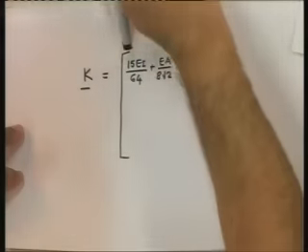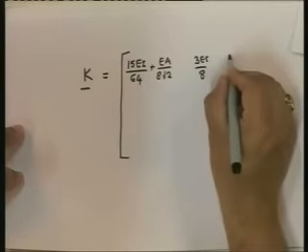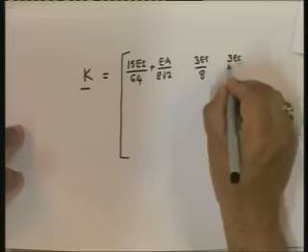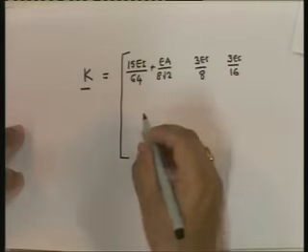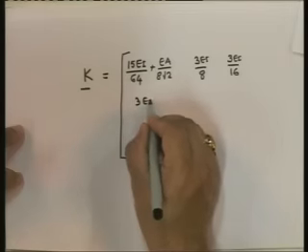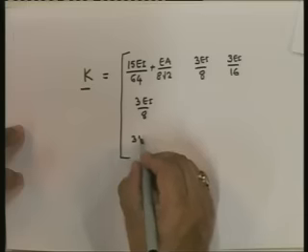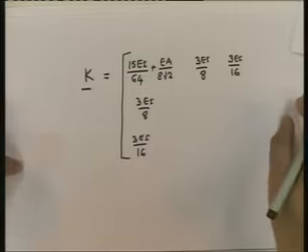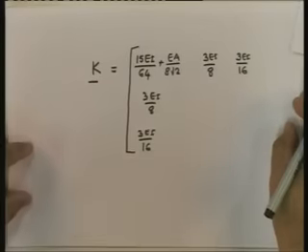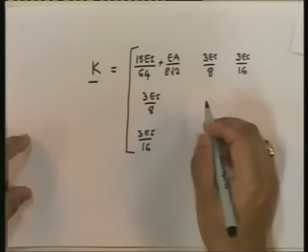The third one is going to be 3 EI upon 16. Then we again look through this, we get 3 EI upon 8, and then 3 EI upon 16. And if we look at the third one, we get EI and 0.